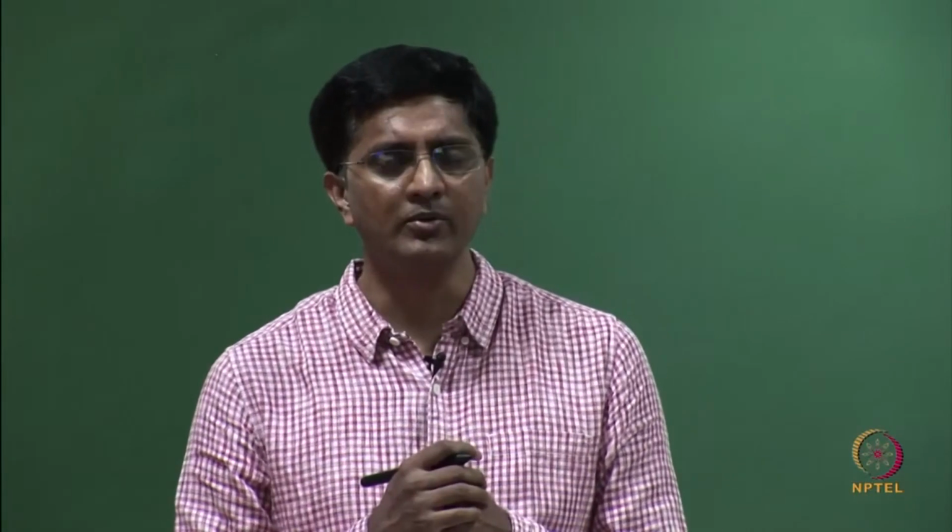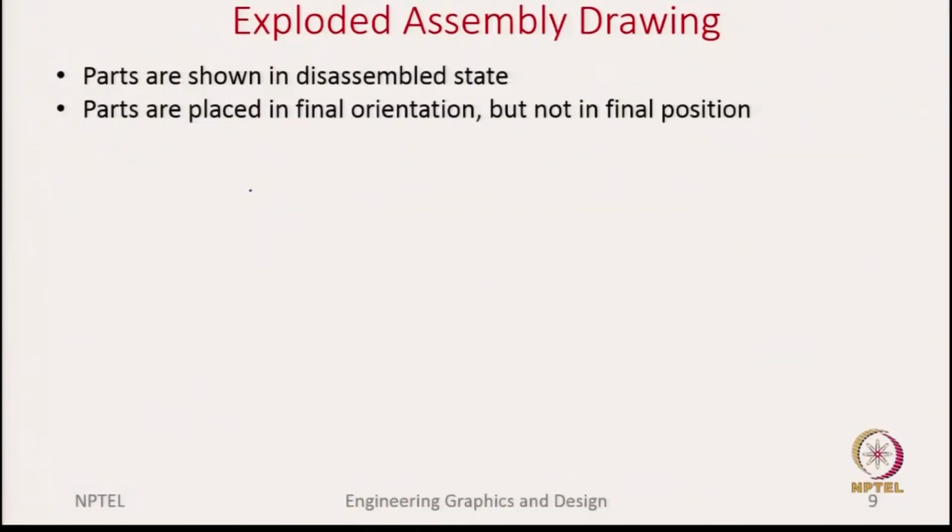Usually this is done for non-technical people, because you can quickly convey your designs to them using pictorials. Essentially what is done in these drawings is you show all the parts in the final orientation, but not in the final position. So, I will show you with a quick animation about what we meant by showing them in the final orientation, but not in the final position.